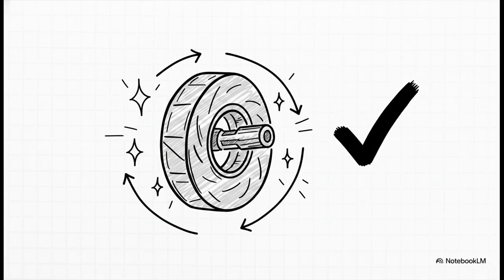So, what should you really take away from all this? It's that circular runout is the definitive key to ensuring your rotating components don't just fit together, but actually perform flawlessly when in motion. It's the ultimate bridge between your design intent and functional reality. Circular runout ensures a single 2D slice behaves perfectly. But I want you to ask yourself, if a single circular cross-section can make or break a high-speed assembly, what happens when we need to control the entire surface of a cylinder all at once? Master the wobble to master the rotation. Next lesson, total runout, controlling the entire rotating surface.